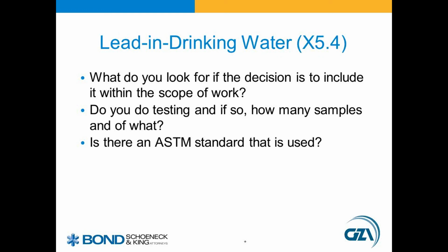Staying with the lead theme, lead in drinking water is also an issue to be concerned about. This was first addressed in the 1974 Safe Drinking Water Act. Lead is unlikely to come from the source, your reservoir or your public water system. It typically enters the water stream from plumbing materials within the building that were installed prior to 1986. These can include chrome-plated brass fixtures and faucets, solder, and lead pipes. And it's more of a concern with the hot water system. Hot water tends to leach out the lead much faster than cold water does.